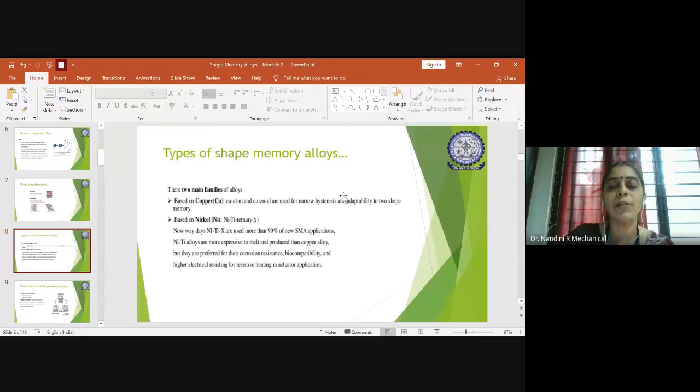And all these things we have studied related to the piezo material. Similarly, even the shape memory alloy will have a hysteresis loop. So it is a closed cycle. So it will start like this and again come back. So you will see the nature of the curve when heating and when cooling in case of shape memory alloy. Whereas in case of piezo, it was the application of the electrical field to see polarization is done, and at the removal of the electrical field you used to see how some amount of polarization is retained. So that used to give you a closed loop. Similarly here, for heating and cooling you will have a very narrow hysteresis loop.